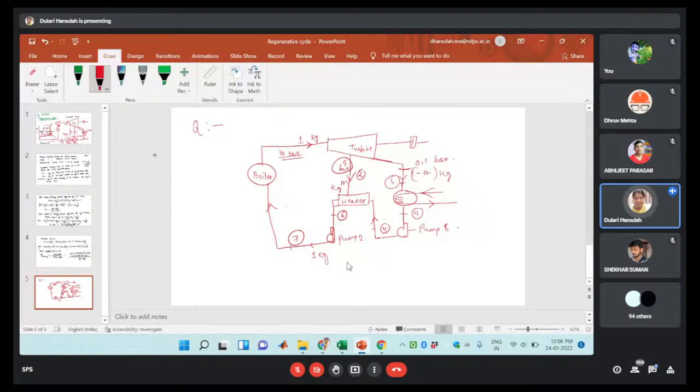So now we can find out what is the thermal efficiency. Okay. So you all draw, or try to use the steam table, because here we already have the pressure. Inlet to the turbine is 30 bar, here it is 5 bar, and in this case it is 0.1 bar. So now let me plot this TS diagram.